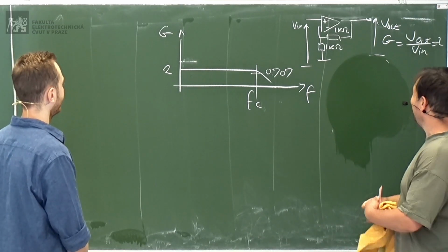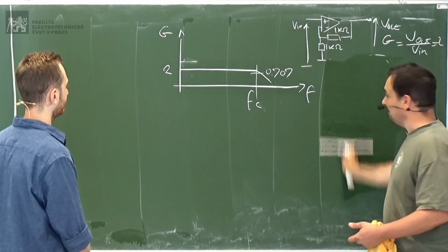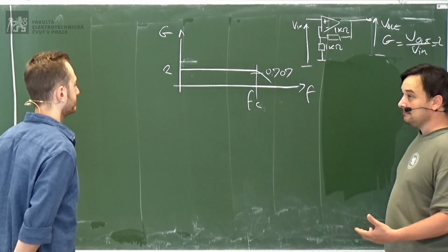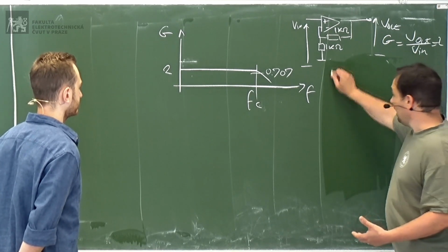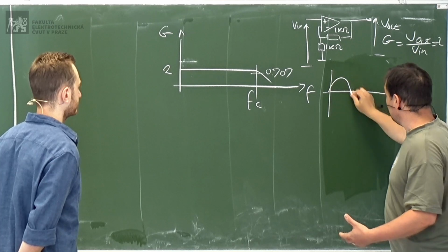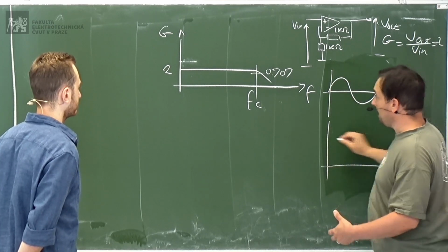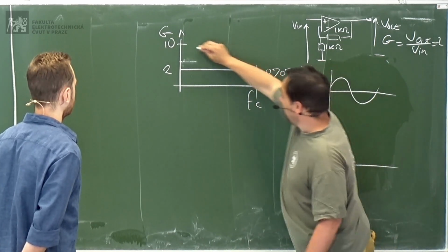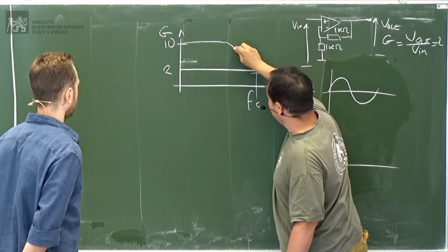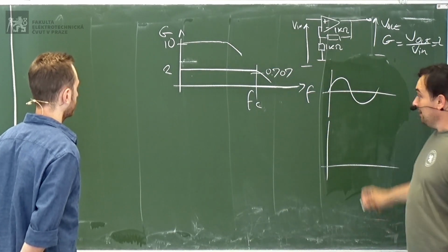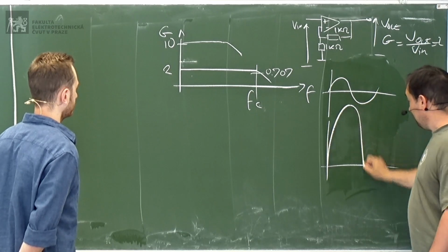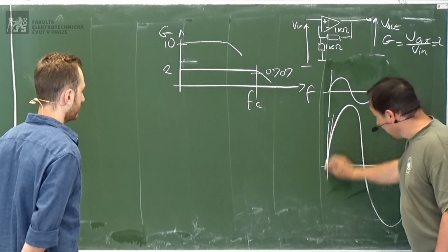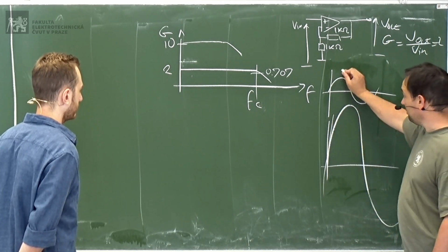I was trying to find that verb. I didn't manage to. Okay, but as I told you, this depends on the gain. So, again, I have the same input, but now I have a gain of 10. The cutoff frequency will be earlier. Exactly. So here I will already start going down because I have to reach a larger voltage. So I would need a higher speed of change for this, okay?